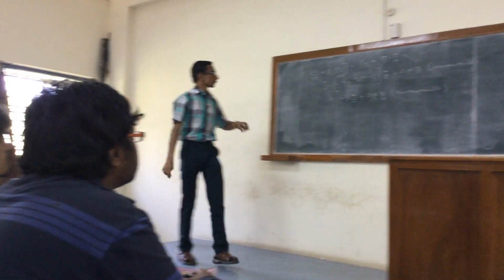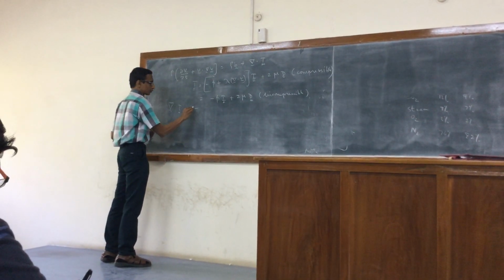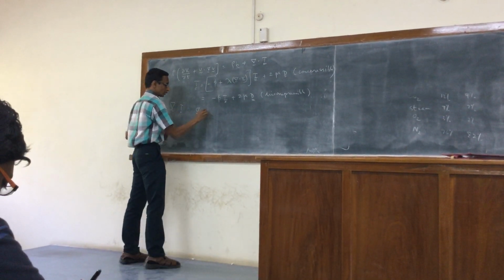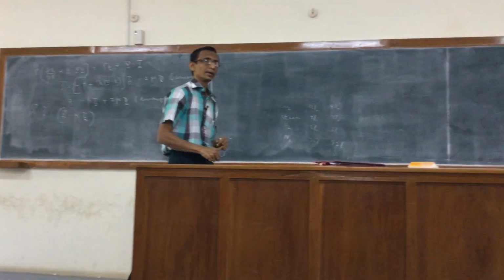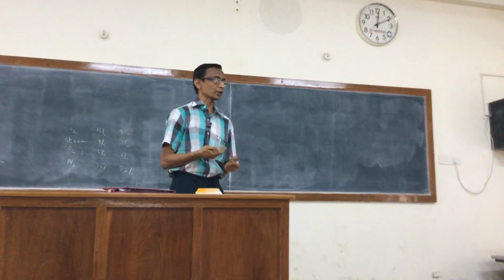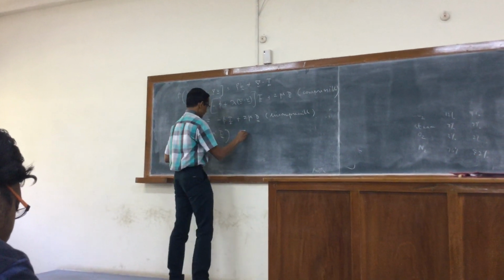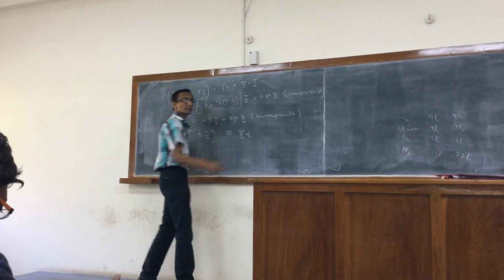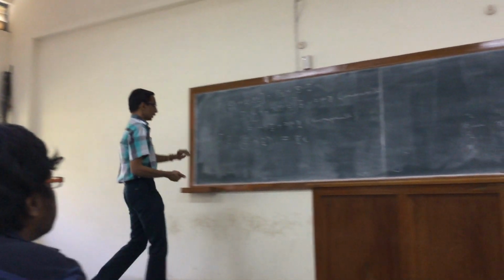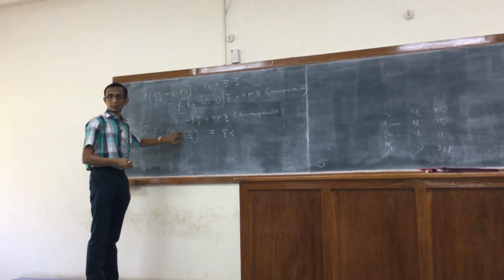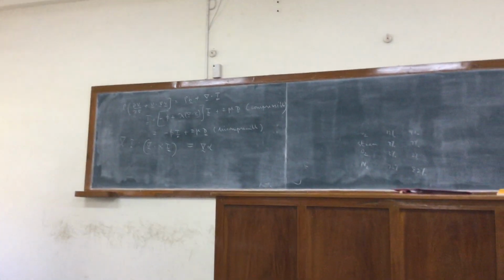So we see that in this case, if I want to calculate the divergence of T, first I have to calculate the divergence of a tensor, which is given by some alpha times I. Alpha is a scalar which could depend on x as well as t, position as well as time. We show that this is equal to the gradient of alpha. So the divergence of the unit tensor multiplied by a scalar alpha can be easily shown to be the gradient of the scalar.